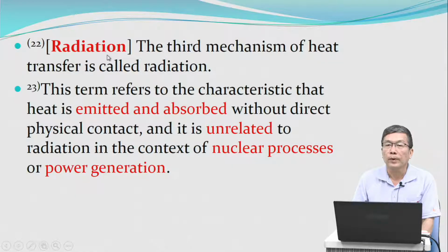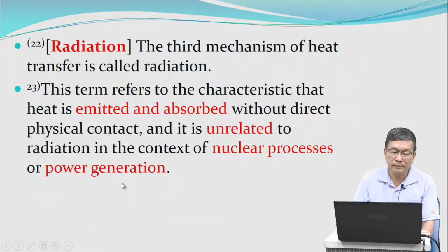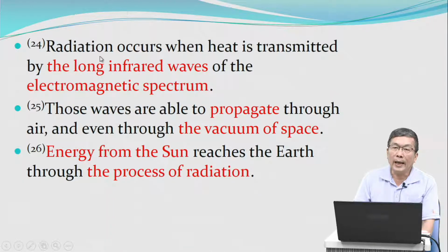Radiation. The third mechanism of heat transfer is called radiation. This term refers to the characteristic that heat is emitted and absorbed without direct physical contact, and it is unrelated to radiation in the context of nuclear processes or power generation. Radiation occurs when heat is transmitted by the long infrared waves of the electromagnetic spectrum.